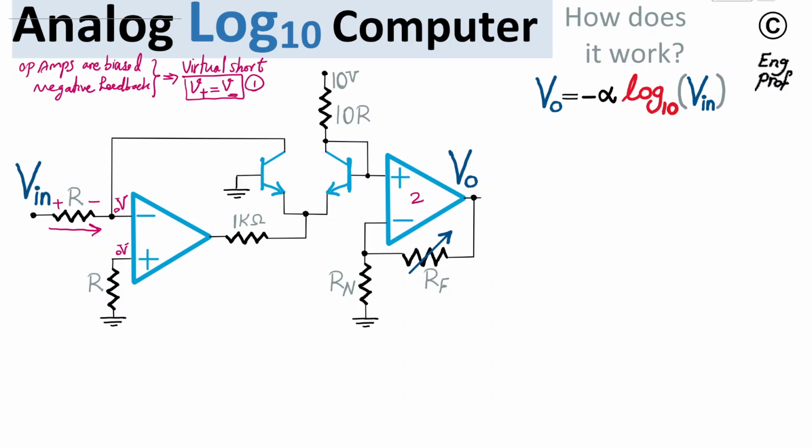And that current is simply I equal to Vin divided by R. Okay, so that's interesting, but the other observation is this current cannot go through the input of the op amp, because a well-designed op amp has practically infinite input impedance, so this current has only one way to go, which is this way toward the collector of transistor T1.